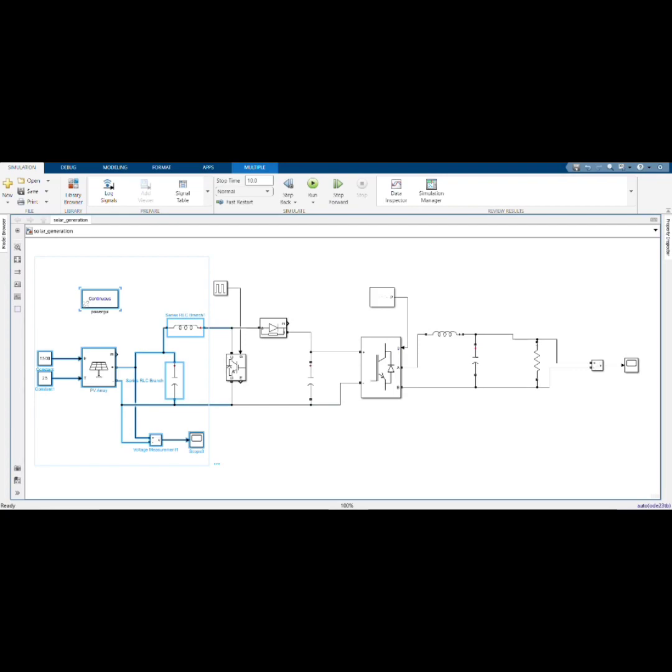In the simulation, we are using an input of 1500 solar irradiance at 25 degrees Celsius. By using this input, we can mimic the output voltage, which can be observed by using a voltage measurement component through Scope 1. At the same moment, an RLC (resistor, inductance, capacitor) circuit is formed by using an inductor as a load for the solar cell. The capacitance of the solar cell is found by measuring the frequency of the damped oscillation that occurs at the moment of connecting the inductor to the solar cell.